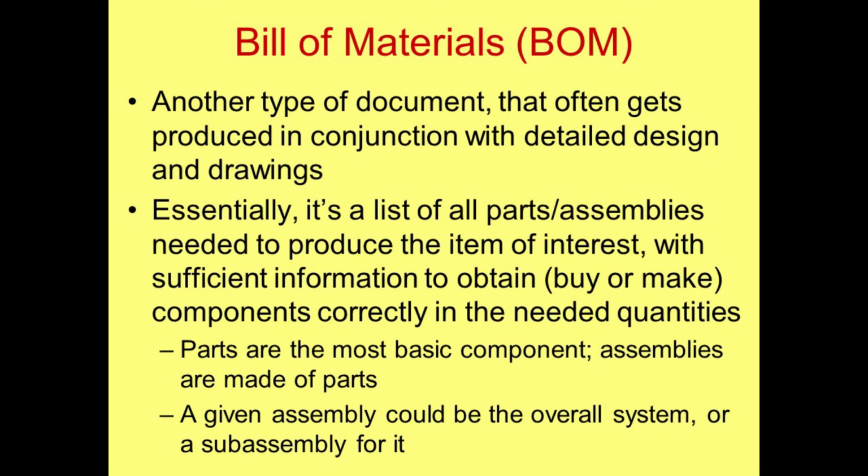For mechanical parts, these are typically grouped into parts and assemblies, with parts being the most basic component and assemblies being made of parts. The bill of materials is a document that's often considered part of detailed design, along with any drawings and any written information. And of course, there are variations of the particulars on these, and a simple internet search will turn up several examples. Also, for chemical products, recipes and formulas can be thought of as somewhat analogous to a bill of materials.